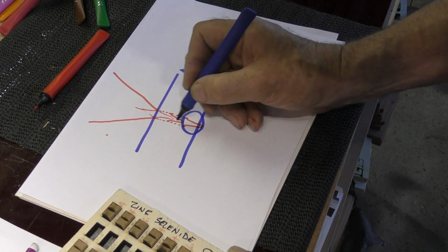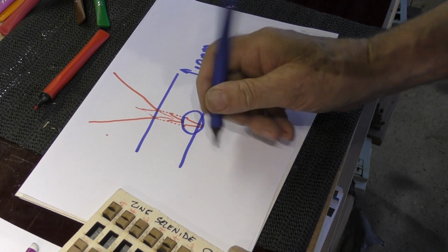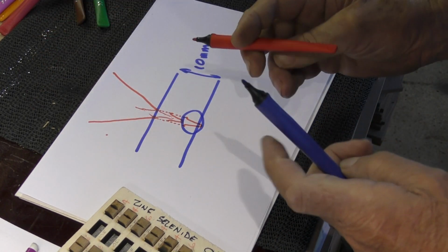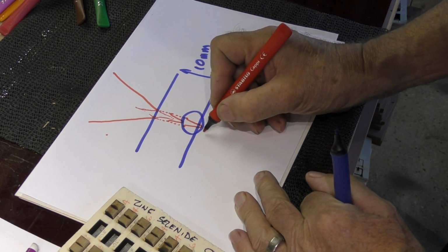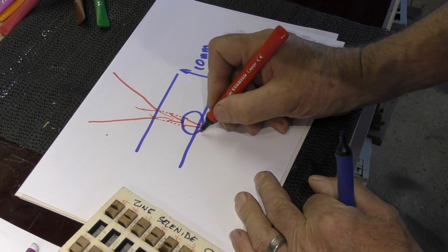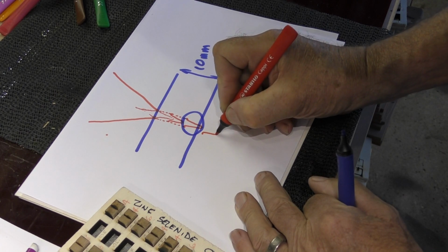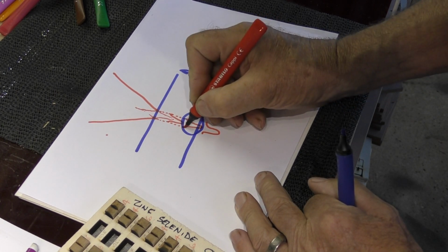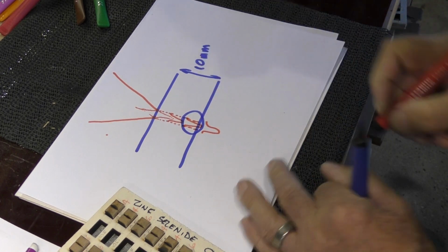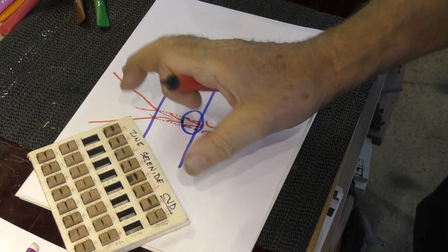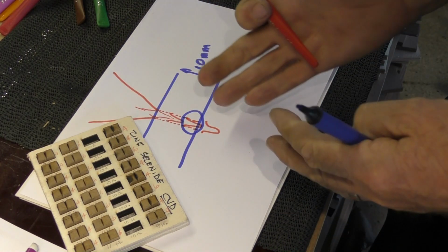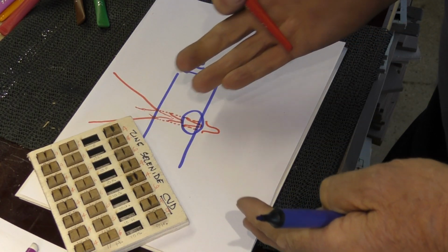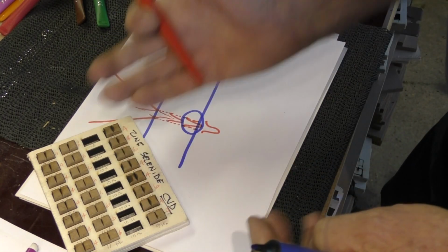In other words, where we've got loads of excess power, the time taken for the power to burn its way through the material is sufficient that this high energy breaks out the bottom here, like this, and actually leaves the parallel cut behind. After studying these pictures, that's the sort of mechanism that I imagine might be operating here.